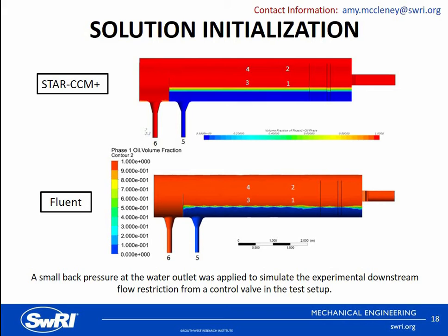So this is the solution initialization, and it was conducted the same in both STAR-CCM and Fluent. The simulations were generally initialized with two fluid phases completely separated within the separator vessel, as shown in these images here. The water height, which is the blue color, was based on the experimentally observed water level for each test condition. This idealized initialization was found to dramatically decrease the computational time required to converge on a steady state condition.